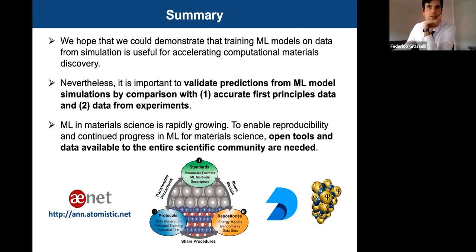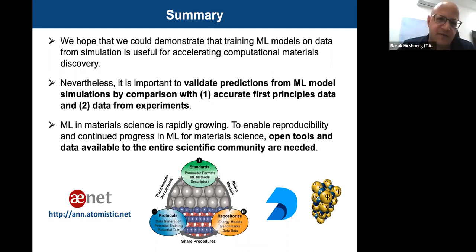So basically all you need is these XSF files that have the geometry, and I'm guessing the energy of the DFT calculation somewhere in them. So in the format, you put the energy somewhere and just the geometry. Then you prepare 3 input files, right? The generate.in and the 2 fingerprints files, and that's it. And that makes the training data set, right? Yeah, everything is provided. It will be possible for you to do the training yourself.